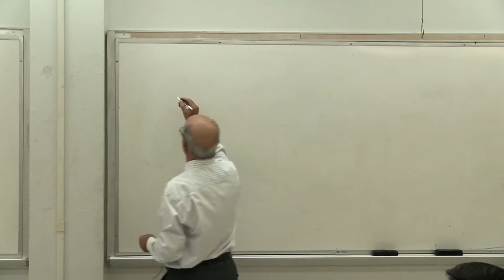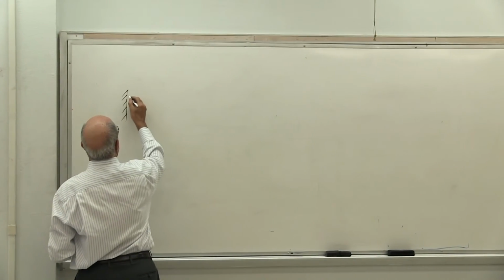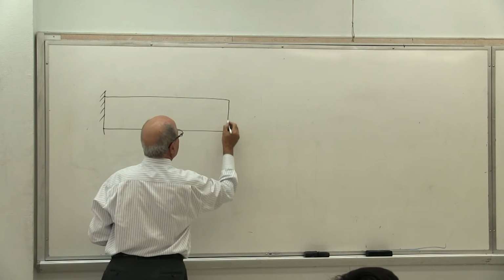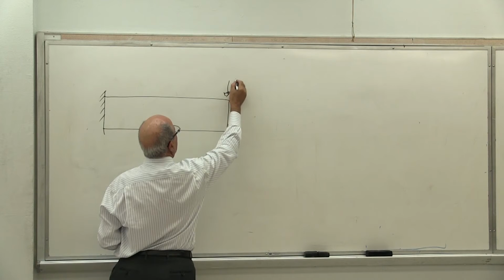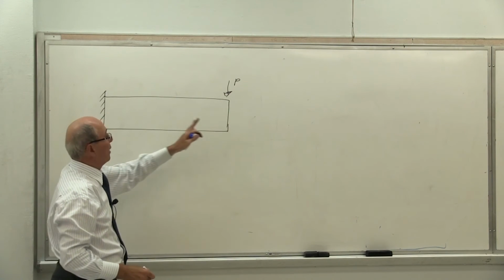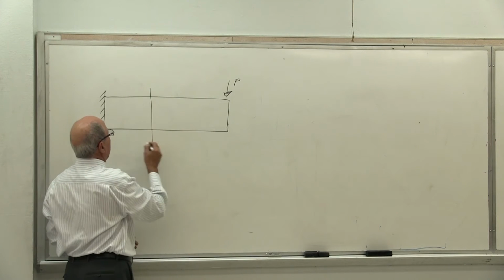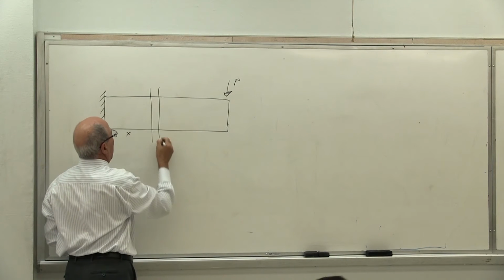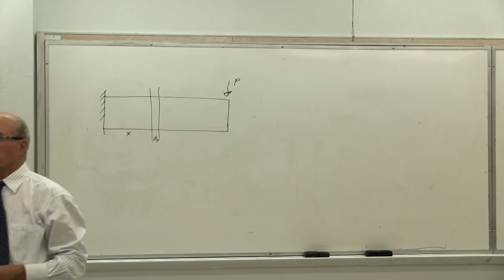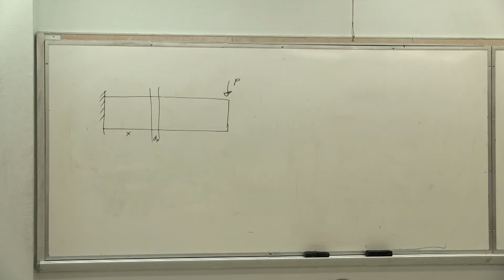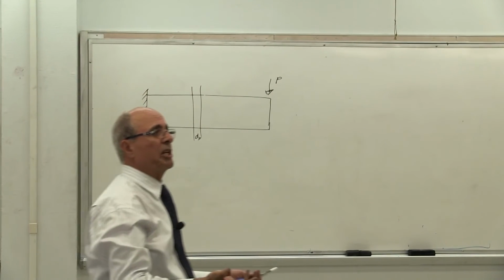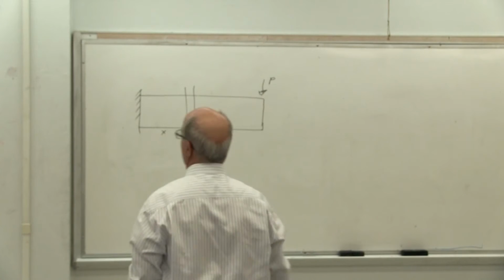Let's go now to bending. This one is a little bit different, but it's the same idea. So this is bending. I just put one load here, P, but it doesn't matter how many loads you have. In this section, when again you are at x and dx, the sigma changes, yes or no? But this time I cannot take a vertical volume only, because in the y direction the stress changes as well, yes or no?